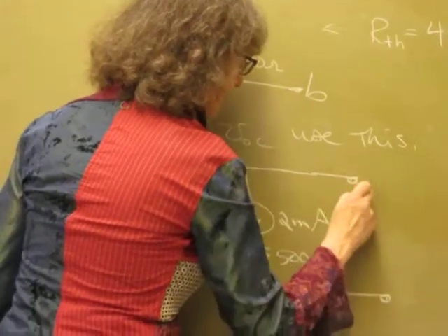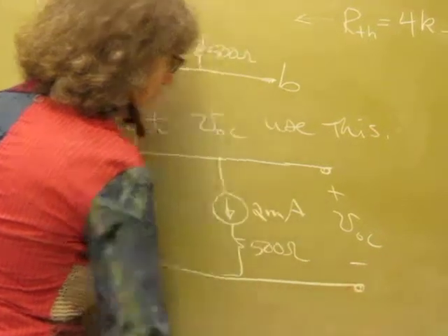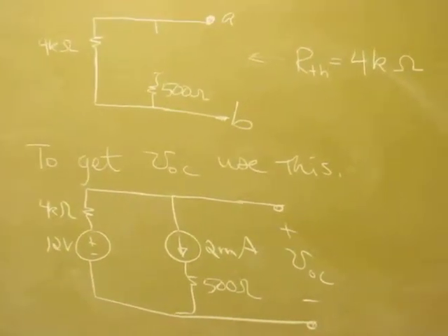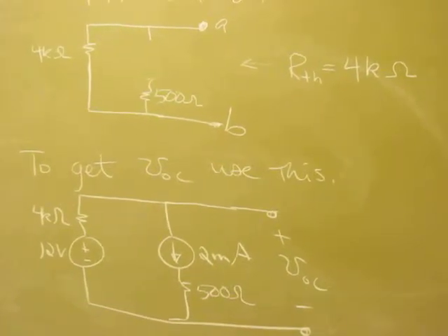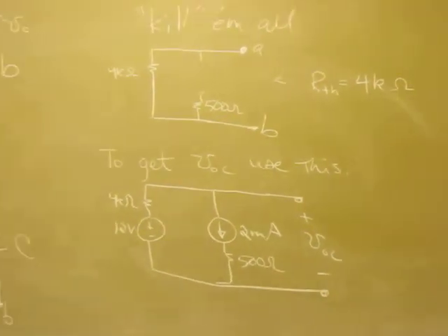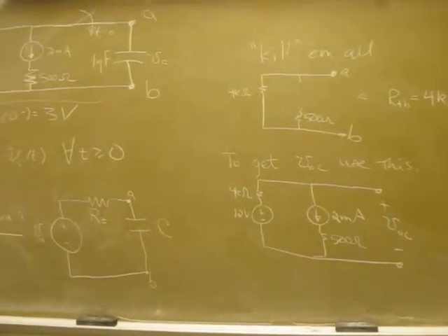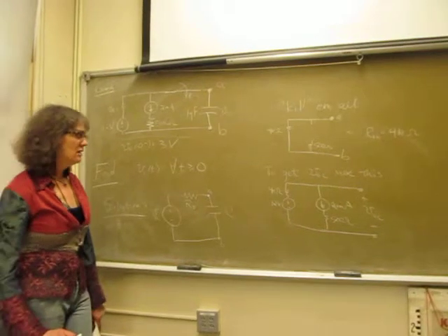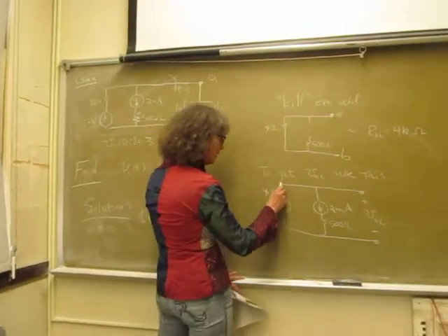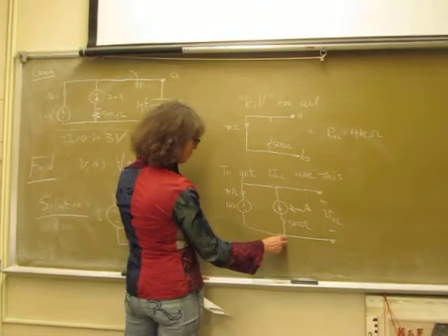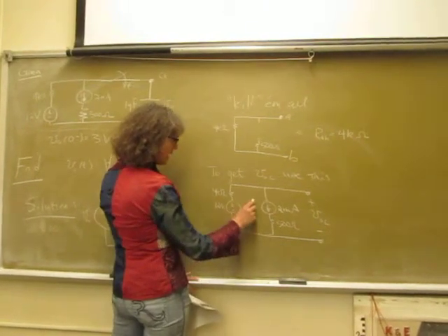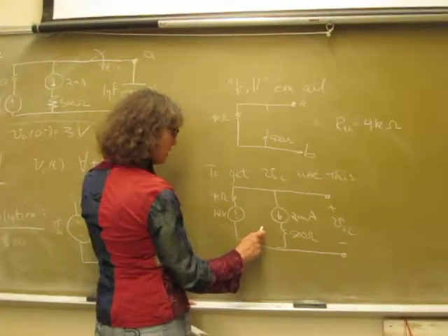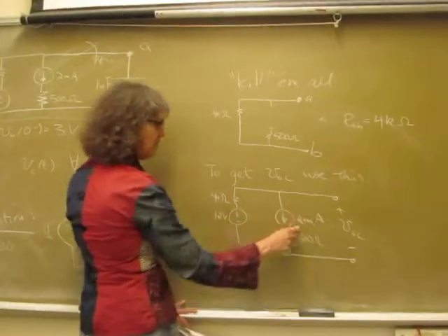And then, we've just got a problem. A regular circuits problem of finding the open circuit voltage, or just finding the voltage there. So, we can use mesh current analysis or node voltage analysis. To me, it looks like this is going to be a lot easier using mesh current, because we've got a lot of nodes, right? 1, 2, 3, 4 nodes. But we've really only got two meshes. So I'm going to go ahead and use mesh current analysis to figure out the VOC.